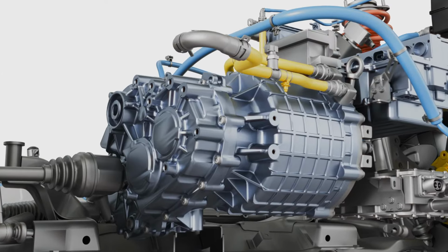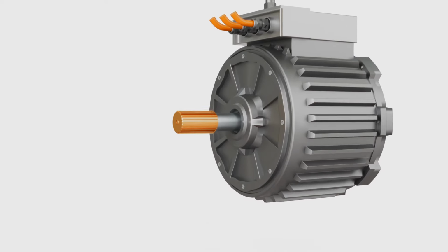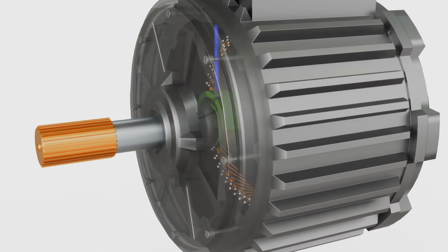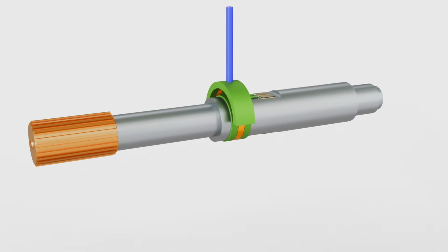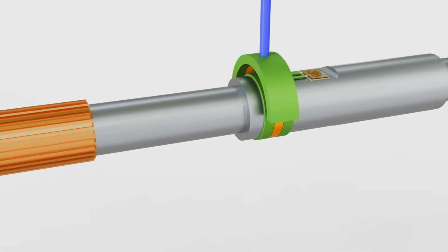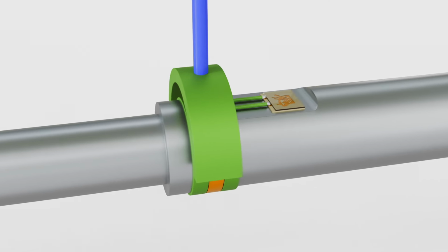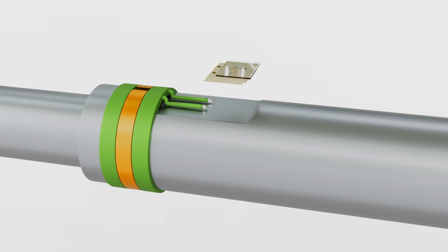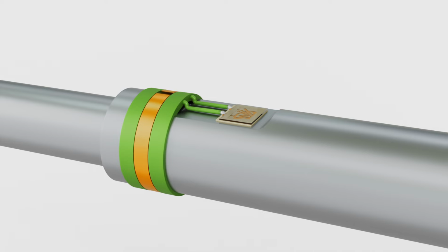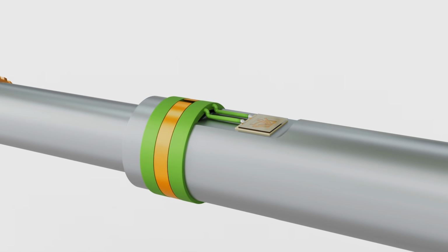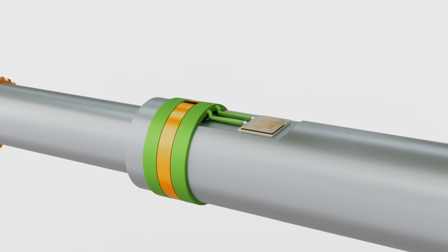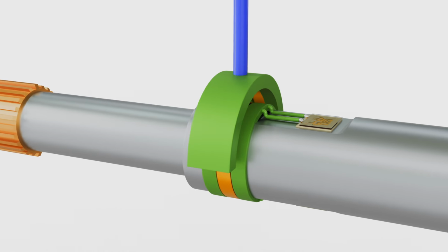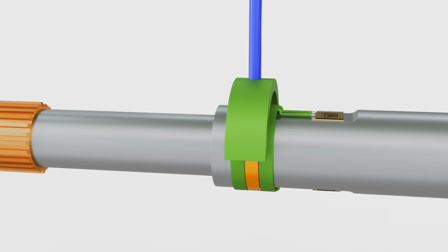Surface acoustic wave, or SAW sensor technology, provides a robust solution for torque measurement in electric motors. A wireless, non-contact system consisting of two main components. SAW sensing elements, passive strain and temperature measurement devices mounted on the rotating shaft with a simple antenna called an RF coupler, and an electronic interrogation unit called a reader connected to its RF coupler.